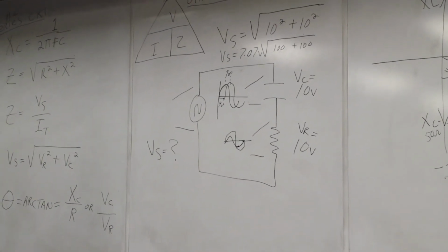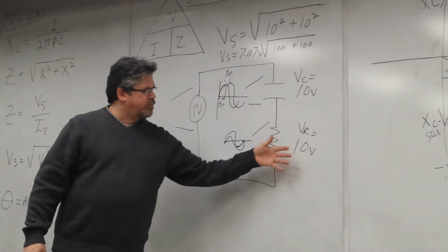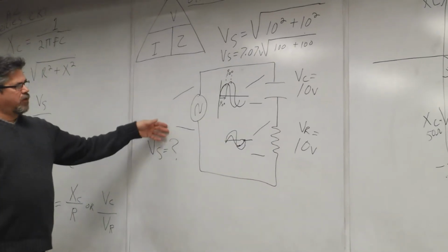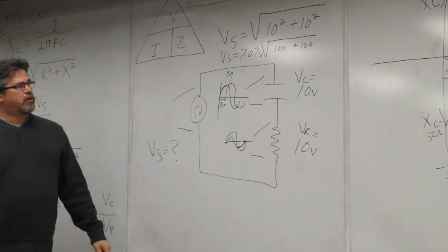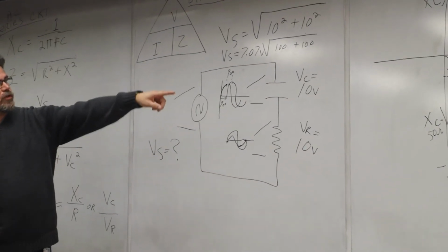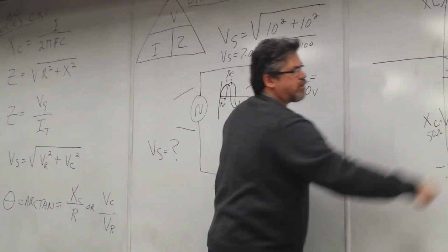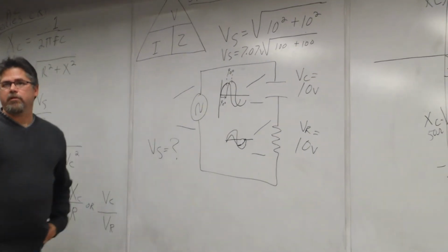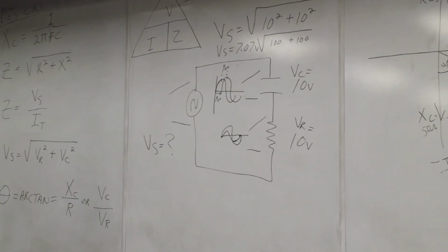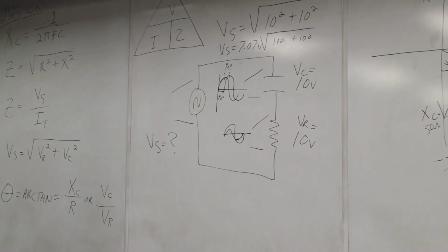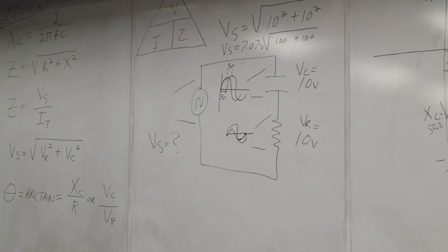But they have to give you those values, right? Yeah, they'll give you these values, and don't be thrown by it. It's pretty simple. You have the other two components on the sides: the voltage across the resistor and the voltage across the capacitor. So all you need to do now is find the hypotenuse. So it's 10 volts across each component? Yeah. And then the source voltage is 7.07. I'm not seeing 7.07. How would you, you can't increase the voltage across resistors.